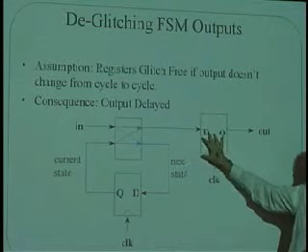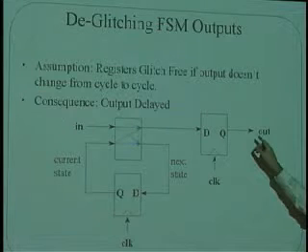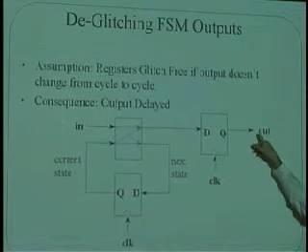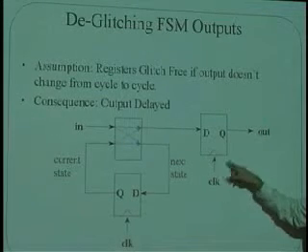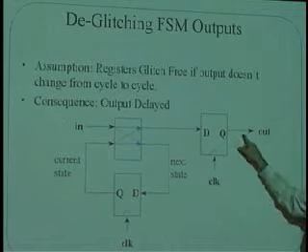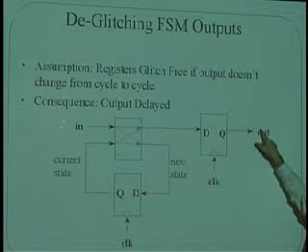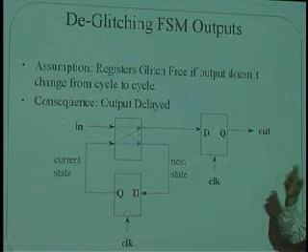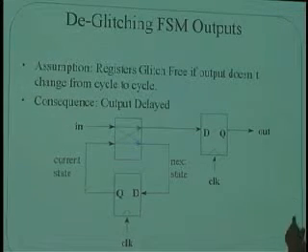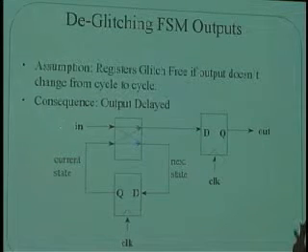Except that flip-flops have a very nice characteristic. And the characteristic is as follows. If the output was 0 before the clock goes off, and the output is going to be 0 after the clock goes off, in other words, if the new picture is the same as the old picture, then it turns out that during the contamination time, a flip-flop actually holds the 0 as well. Okay? In other words, if I take a picture with the camera, right, and then I take another one and the picture is exactly the same, during that time where it's developing, it still has the same picture.